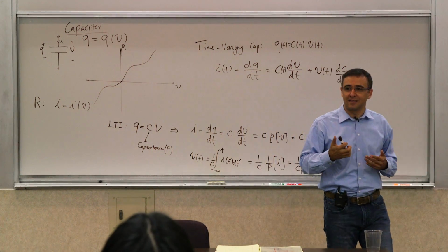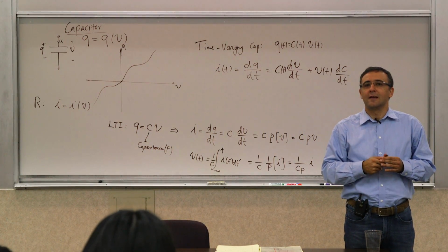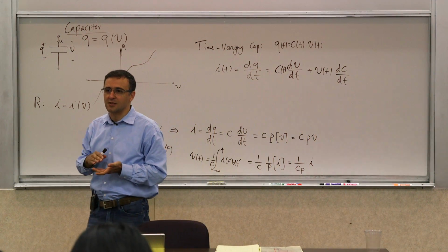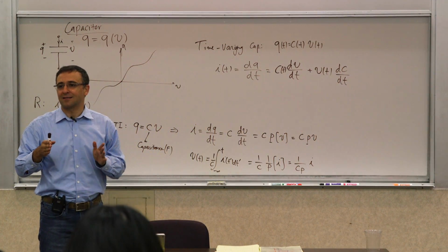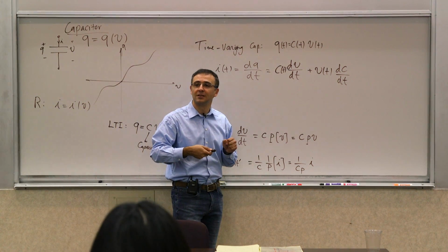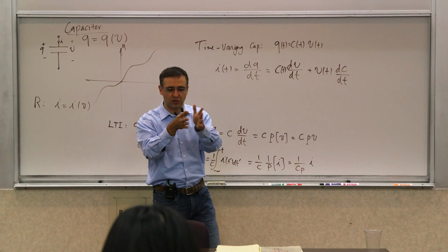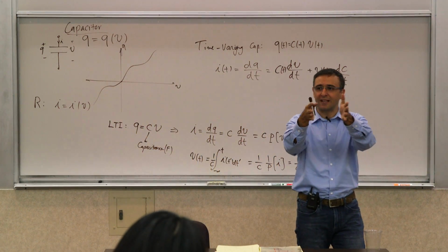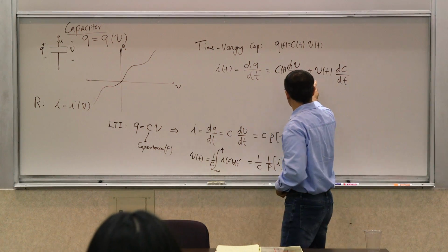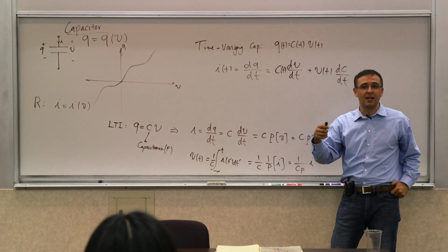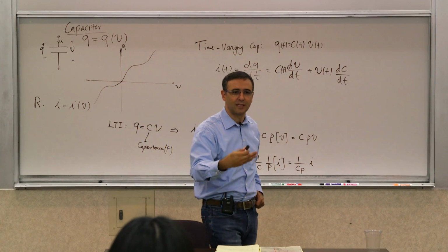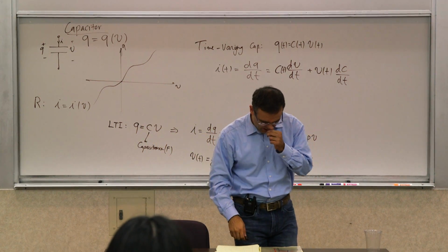There are many different ways of doing that. There are other ways to make this, and you will see later on. For example, p-n junction diodes or MOS capacitors have a voltage dependent capacitance. So by changing that capacitance, you can actually create a time-varying capacitor, because where the charges actually are changes. So the effective plate spacing is changing. And you can use that with this equation to do some interesting things, such as parametric amplification and parametric oscillation. But again, those are for later.